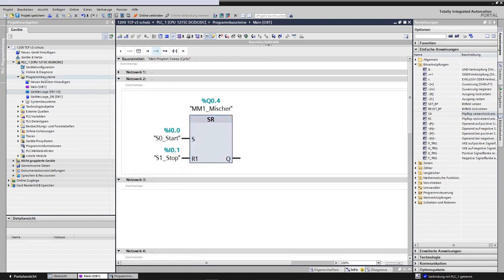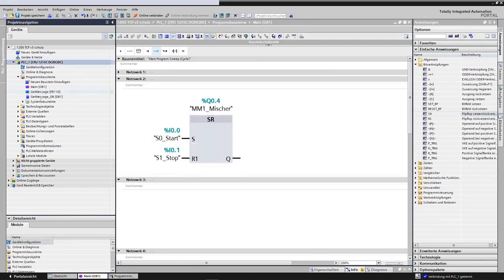So now let's get to the actual task, whether this works or not, as I have programmed it here. One small thing is also important. When I click on the entire folder here, I transfer everything that is in my project. If I only click on the component, I only transfer the change in the component. It makes sense to transfer everything the first time and then see where I currently stand. What have I changed? Is it even worth transferring the entire project again, or can I just transfer the change? This small thing that I may have changed, is that enough?